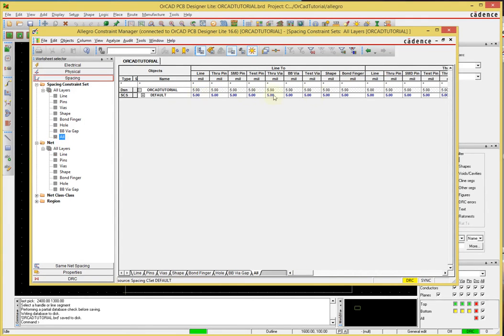And notice that everything says 5 mils, and usually that's okay. But you need to check with your PCB manufacturer. Every PCB manufacturer has a set of constraints: how much spacing, how wide the traces can be, how small they can be, how close any feature can get to another feature, and the manufacturer will state this on their website.